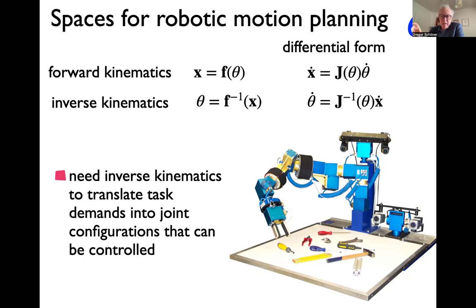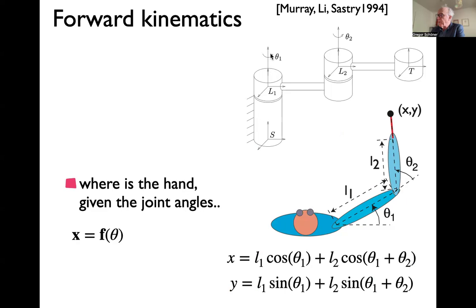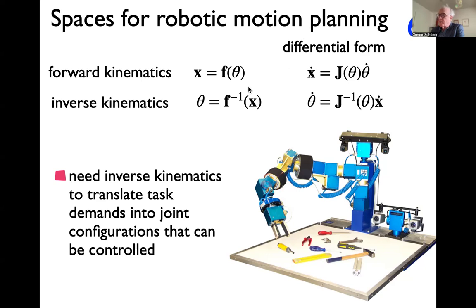The individual segments are rigid bodies, which can be shifted in 3D and rotated in 3D, so they have 6 degrees of freedom. But when they're mounted in a robot, they typically have only 1 degree of freedom, because they have a revolute joint with the previous segment, and then they can only rotate around one axis, where the revolute joint turns them, like this one here, around one axis. And so they have only 1 degree of freedom, right? So per joint, you get 1 variable that you can control.